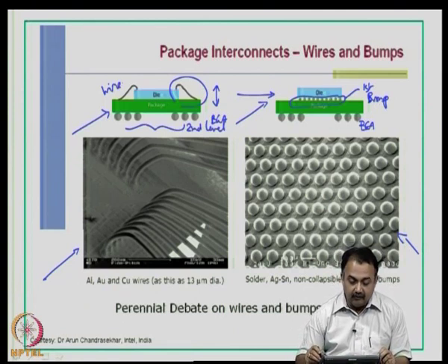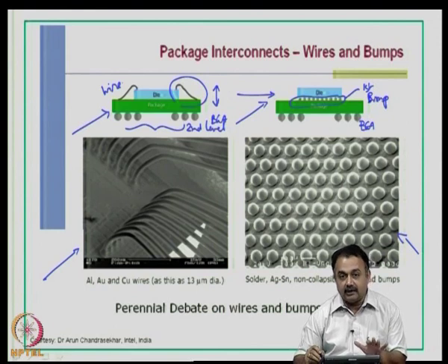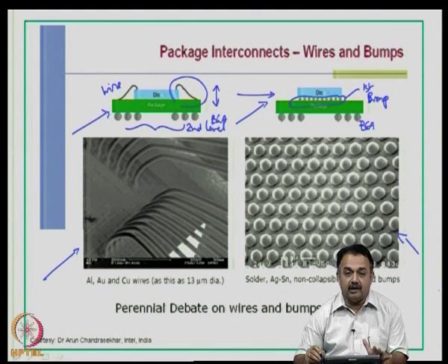Okay. We are not going to consider here a wire and a lead frame, because typically that is low dense. These two options that I have presented here in this slide are typically high dense packages, because it is ball grid array which enables you to work at low pitch, but the first level interconnect here are varied. One is a wire, the other is a solder bump.